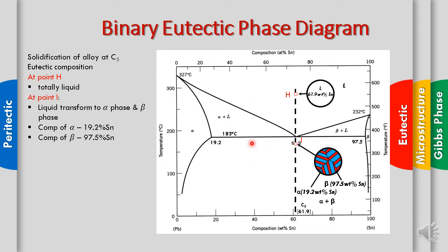Okay, here the microstructure consists of the primary alpha. We have the bigger alpha in the schematic diagram. The microstructure has alternate layers of alpha and beta, where we can see a lamella.